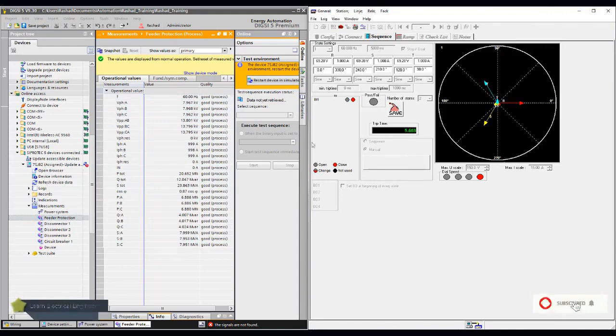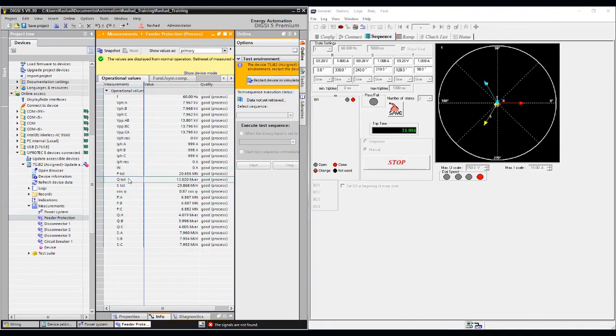Of course, I expect that the angle here, the current lags by 30 degrees, so you have it lagging by 30 degrees, meaning the voltage angle is 0 and the current is minus 30, which falls in the first quadrant. So I expect that both the power value and the reactive power value will be positive. Alright, so cosine 30 is root 3 over 2, which is 0.866, and sine 30 is 0.5. So you'll find that the power value is greater than the reactive power value.